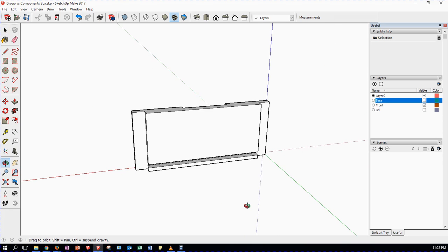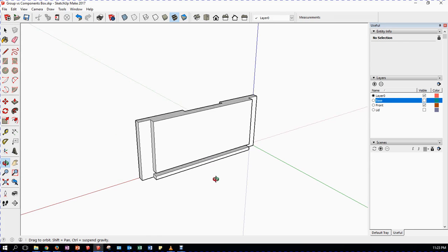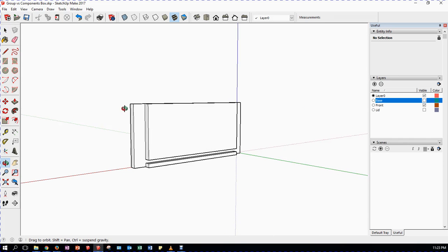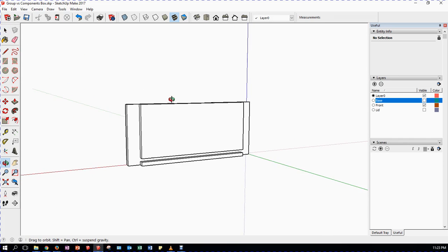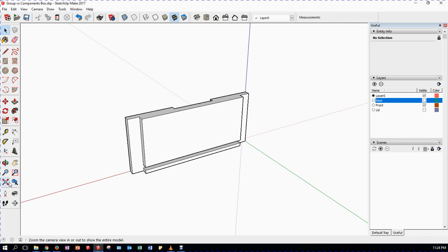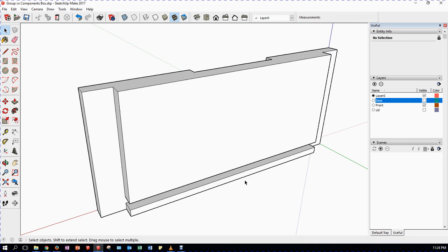So now I have a piece of wood here and I need to dimension it in some way. I need to show enough detail. Now I may choose not to dimension that at this stage. I may just put a note there that I have a finger rebate, and we may dimension it something like this, and I'm going to zoom extents to get some idea of whether it shows me all the detail I'm looking for. Not bad. So now I start adding dimensions.